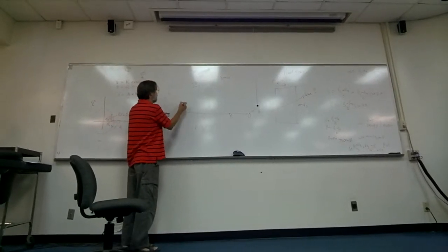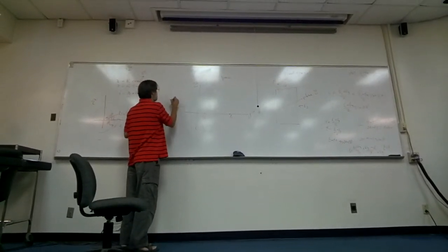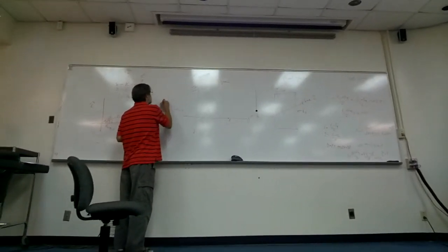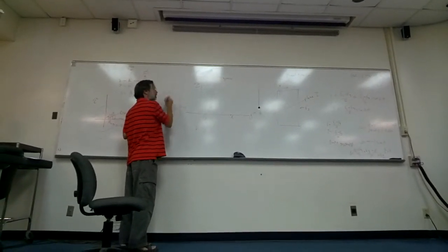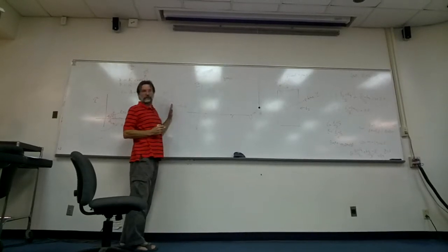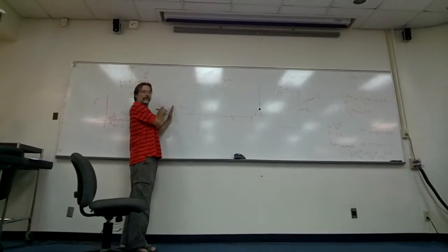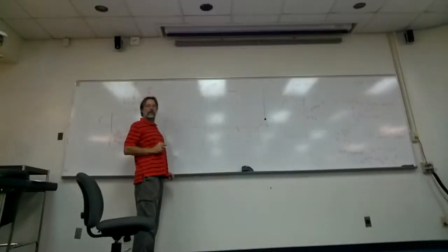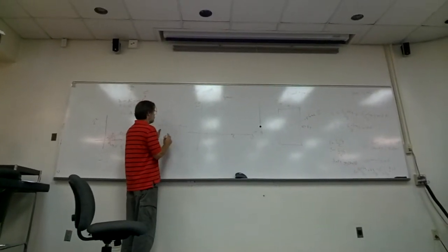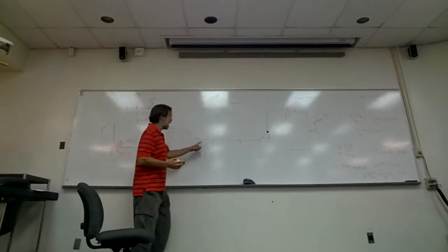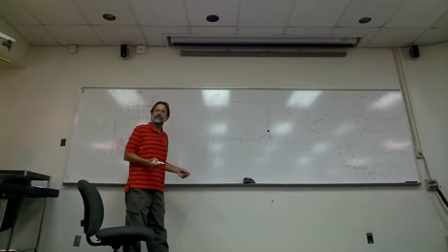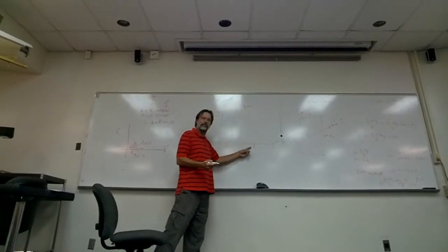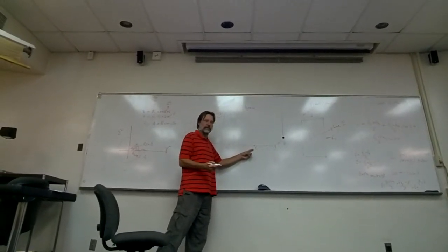When theta is 90, I'm on this plane. So I'm perpendicular to sigma 3, which also has to plot there, right? So those are the principal planes. They better plot there since that's the way I set it up. That's the way it's supposed to be, right? But these two values then have no tau value.